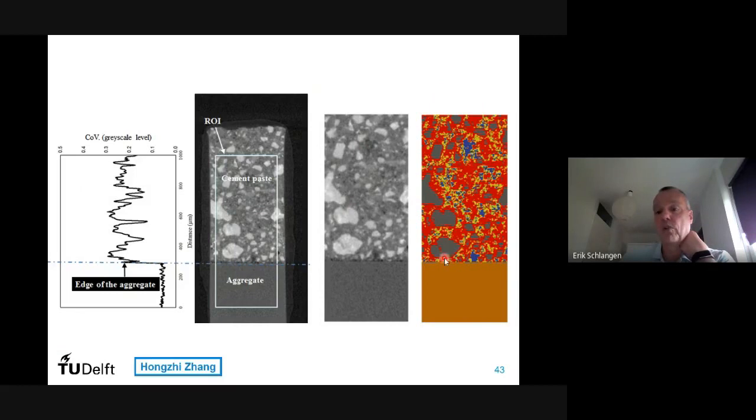And you see that the porosity is higher at the interface. What you also expect, that you have high porosity there because your cement particles are not nicely distributed. You have some more water, so you end up with a higher porosity, which creates this kind of weak interface between aggregates and cement paste. Of course, there are a lot of ways to improve this interface, but we didn't improve anything. We just tested this as we made the material.